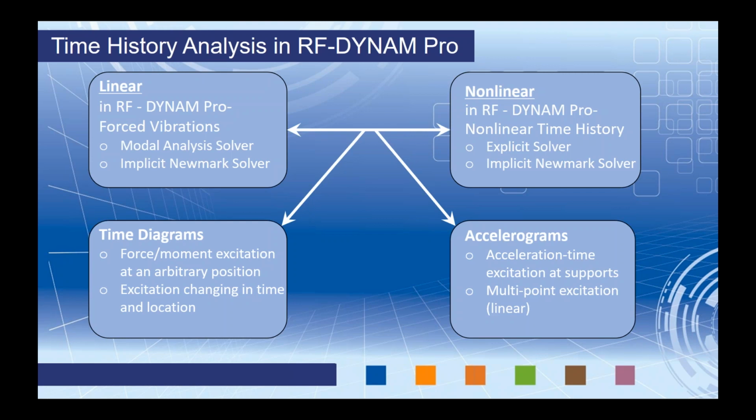Now, as far as accelerograms, this can be taken into consideration with time diagrams that can be imported from a library of earthquake recordings, which we have available directly within the module, or it can be user-defined. The difference here is that this is an excitation at the supports. A multi-point option is available as well for the linear analysis only.